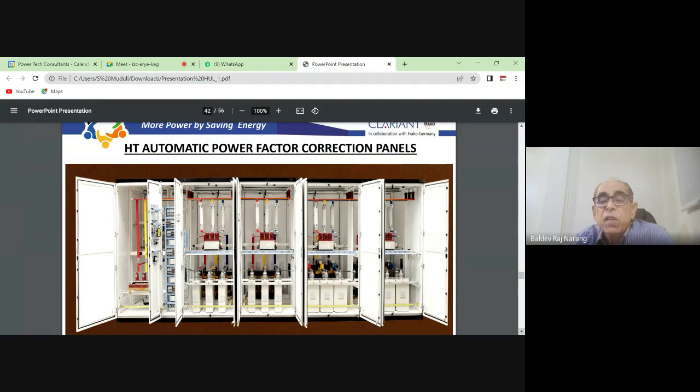Whatever harmonics are generated, we conduct the study, we find out which harmonics they are, and then whatever is possible, the fifth and seventh, the passive will take care. And suppose there are different harmonics, a very odd spectrum. The active filter we can tune for that, and that will take it out of the system. Even during starting itself, it will do its job. So there is no special separate solution. The same solution is there, but it works only whenever the harmonics are there.